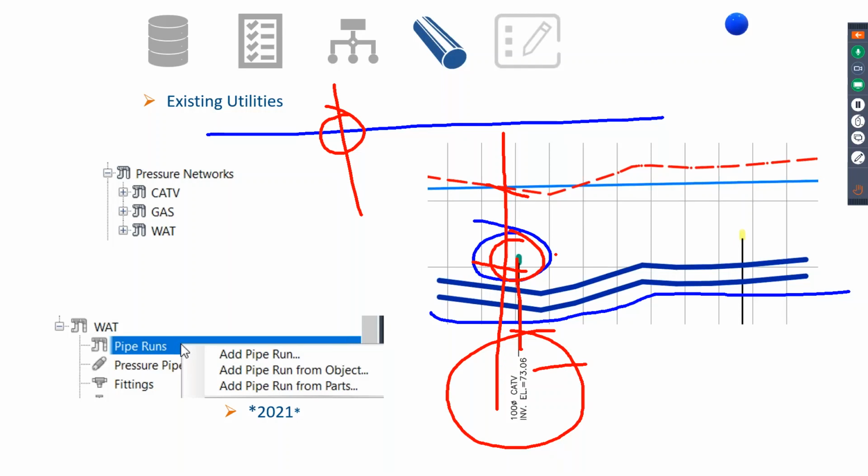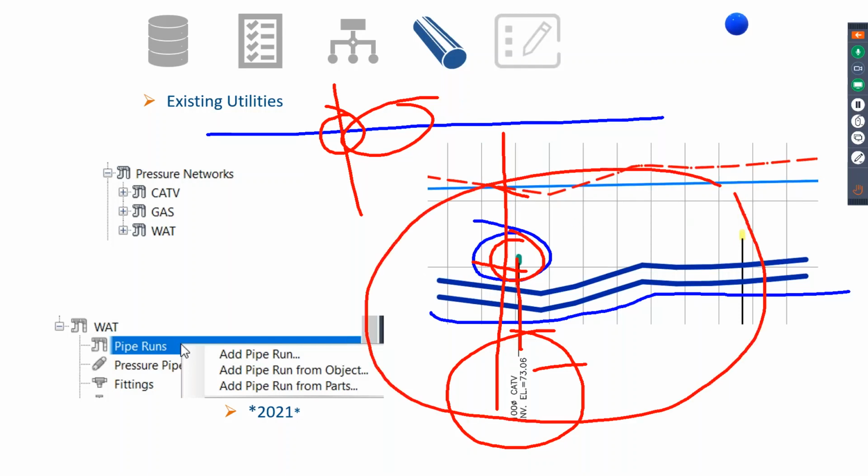And so in the project that I saw with 160 crossings, if they took 2 minutes each, that's 320 minutes. That's a lot of work. It's over 5 hours of just showing this. Guess what? If you'd modeled these things correctly, using Civil 3D parts, putting them in profile takes exactly 0 seconds. If you've modeled them correctly and if your styles are set right, you're going to be saving yourself a ton of time on a project like this, at least.